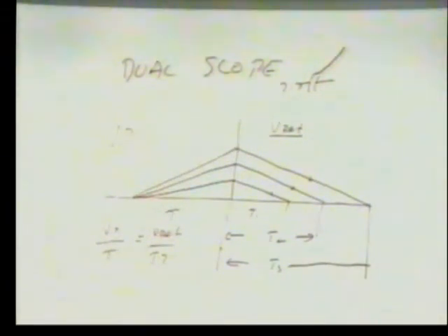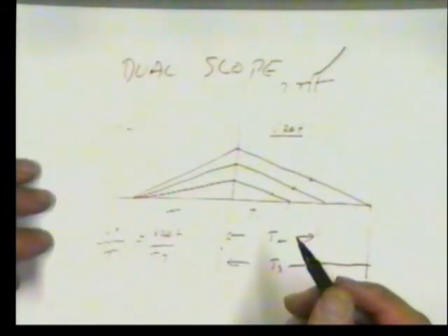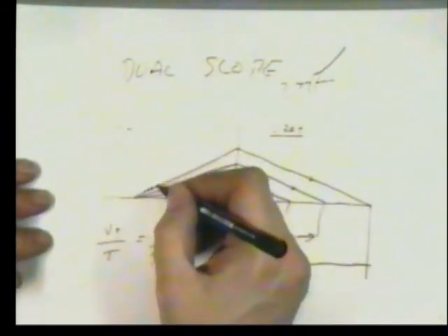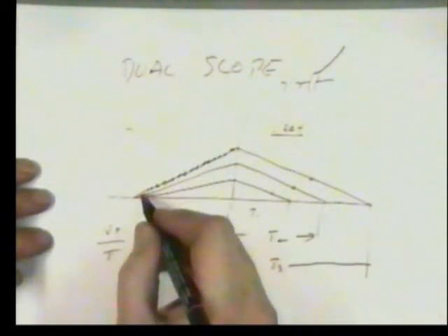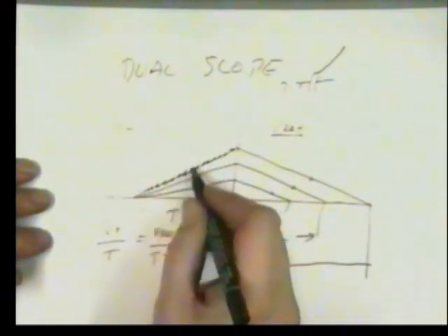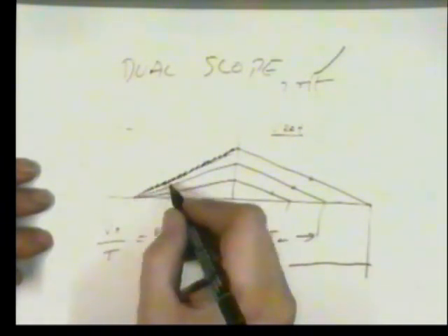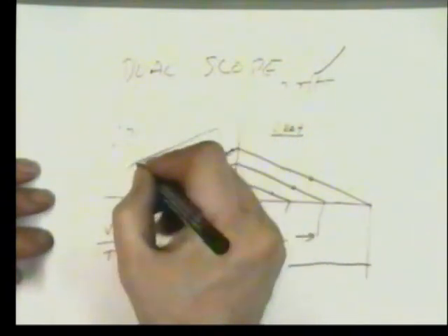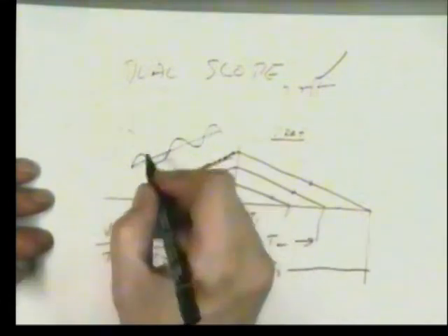If there was some noise on our system, noise normally comes in general as a high frequency interference. If there's some noise on our input signal, the effect of that noise is that it will be averaged out. Because we're charging up, let's look at this in finer detail. And here's our noise, and we're charging up our capacitor.